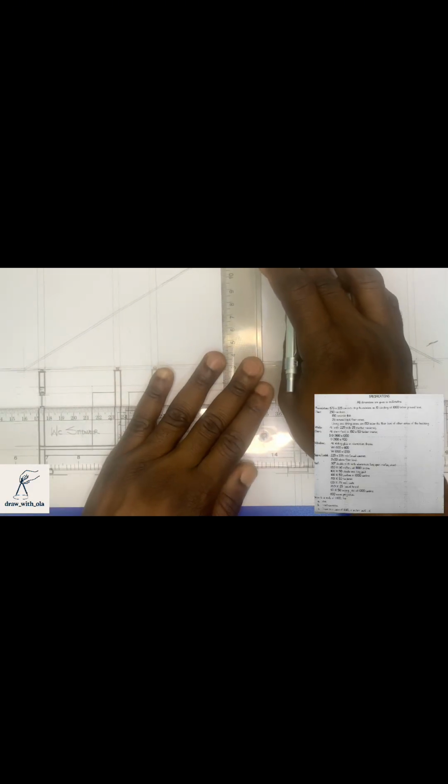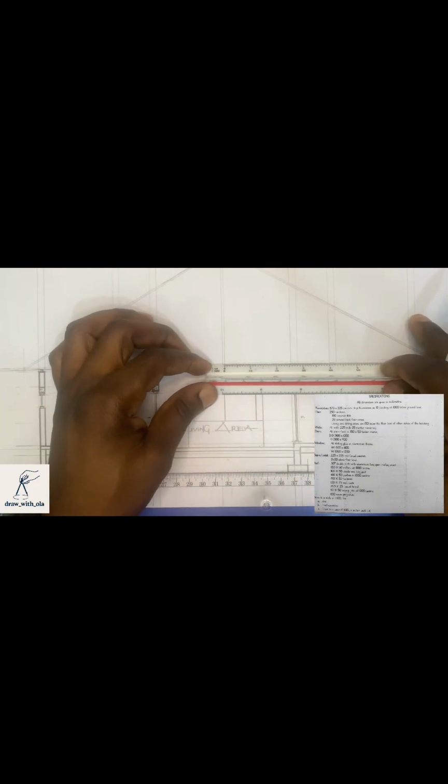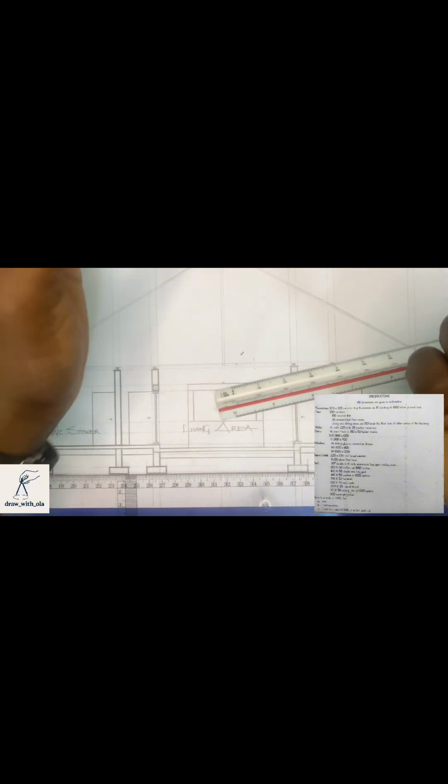All right, next, project lines from this point together. The king post, usually situated at the center. So this is our king post, and we're told it is 100 by 50, so you can see this is 50. They are at 1000 center to center, so we produce backing posts for every 1000.